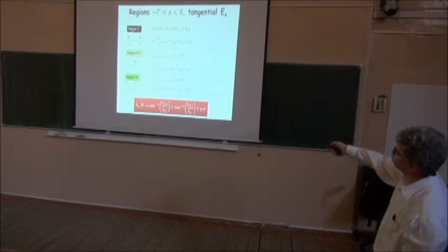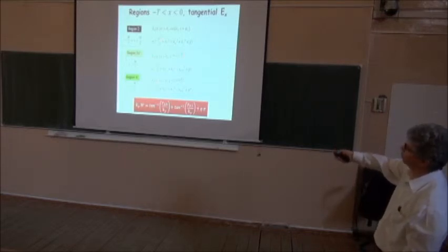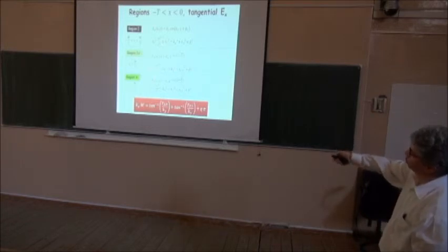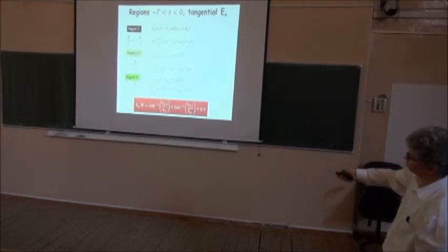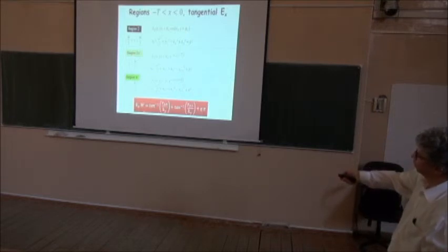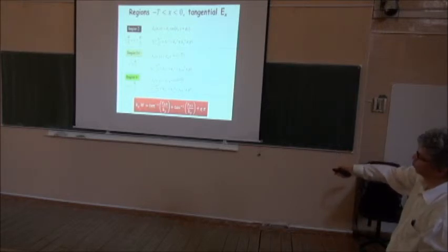And with those expressions, that defines what we had before, that my tangential components are in an electric field, and that's what defines the solution of the TE mode. So the dispersion equation now for the TE mode, and the relevant change here is that my confinement is between negative W/2 to W/2, so that makes the thickness of that slab as W.